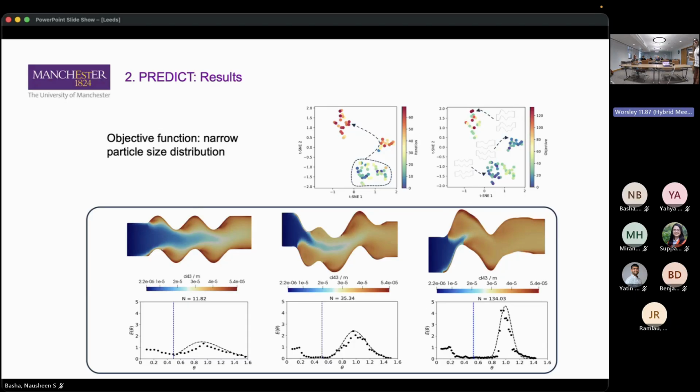If you have a good uniform distribution, the crystal size would be narrow. And typically what you want is the crystal size to be narrow, which is good for therapeutics, which is good for manufacturing, which is good for all sorts of downstream processes. So the pharmaceutical industry would want the particle sizes to be in a narrow range.